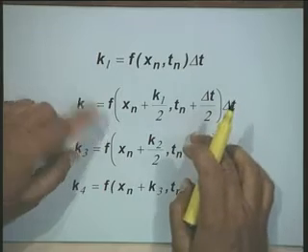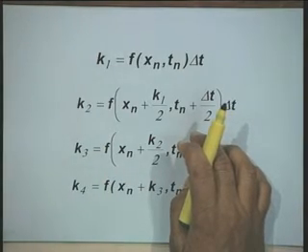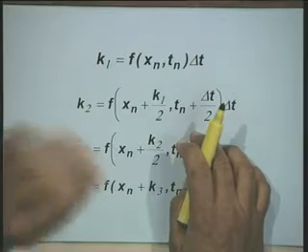In all the differential equations we come across, the time is not explicitly available in the equation. That is, time is an implicit function. Suppose I solve this swing equation, on the right hand side, when I evaluate this function, it is a function of delta and so on. The time is not explicitly visible, but it is implicit, because delta corresponds to a certain time.